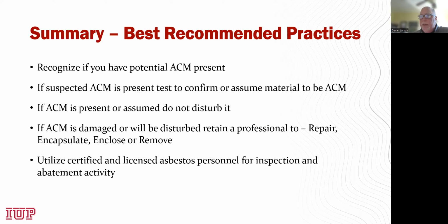So again, in summary, just what are the best recommended practices? Recognize if you do have asbestos in your building. You need to have enough knowledge to know whether your employees are working with something with asbestos, or whether asbestos is present, maybe in your boiler room. Again, you need to have the knowledge to know that it's there. If it's present, you may want to test it to confirm it is asbestos, or you can just assume that the material is asbestos. If it is present, do not disturb it.